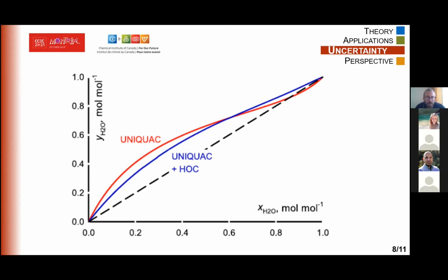So how do we avoid this? We need to consider the association of the acetic acid in the vapor phase. And the UNIQUAC model, which is a gamma model, does not consider non-ideality of the same molecule, only non-ideality between different molecules. So in this case, the Hayden-O'Connell model calculates the vapor association by calculating the fugacity coefficient.